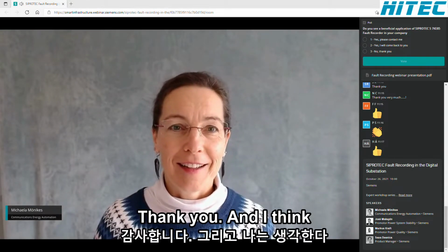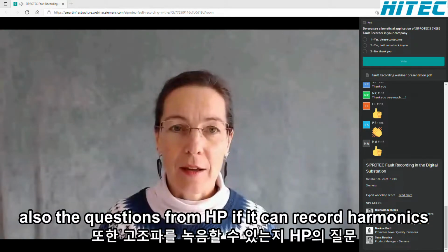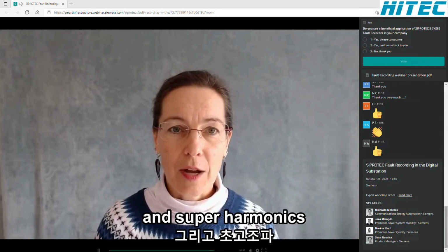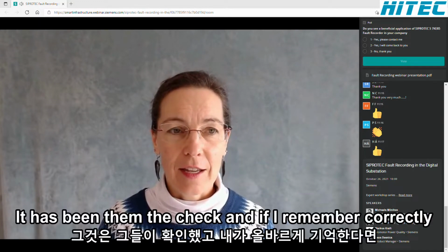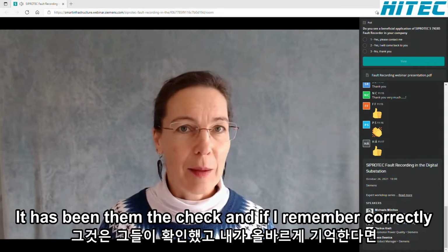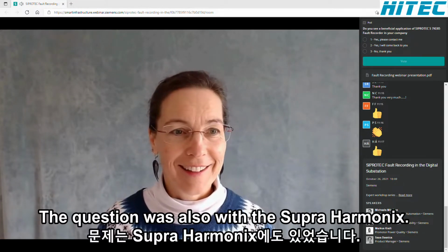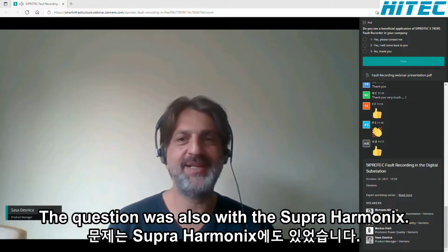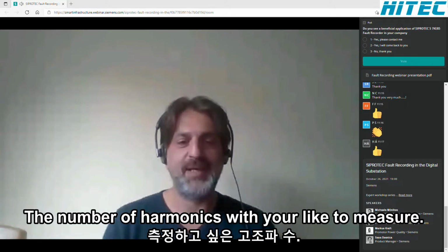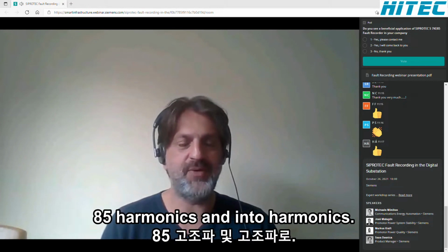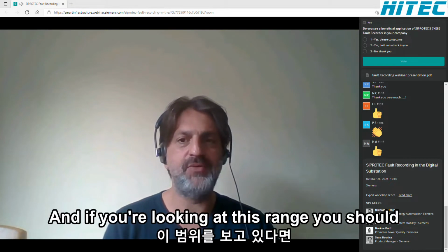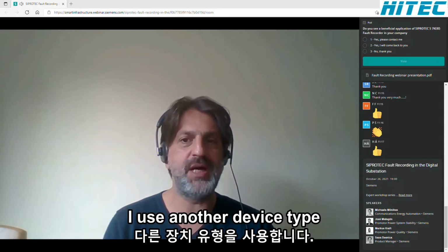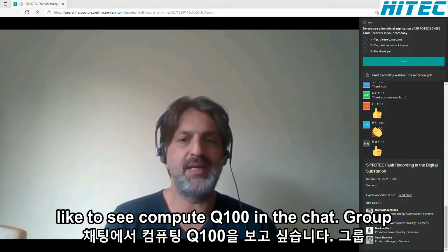Yes. Thank you. And I think also the question from HB, if it can record harmonics and supraharmonics, voltage and current, that has been in the chat. And if I remember it correctly, the answer was yes, right? This is yes, but in the chat, the question was also about supraharmonics. This depends on the number of harmonics which you would like to measure. That means we are able to measure with the 7KE85 harmonics and interharmonics up to the 50th of current and voltage. And if you are looking above this range, you should use another device type like the SICAM Q100.